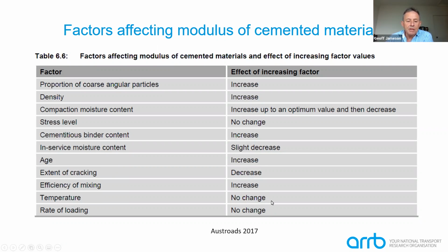And we assume these materials' modulus doesn't change with temperature or with rate of loading, unlike what we'll talk about later with asphalt, where we do recognise how the modulus varies with temperature and loading rate. For these materials, we don't allow for that. And the other aspect, in terms of stress dependency, is that we make the assumption that the modulus of these materials doesn't vary with the applied stress level.